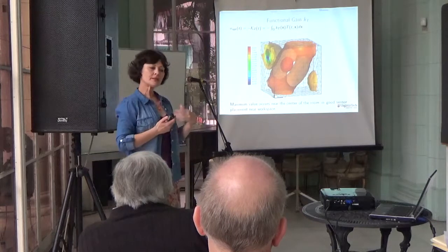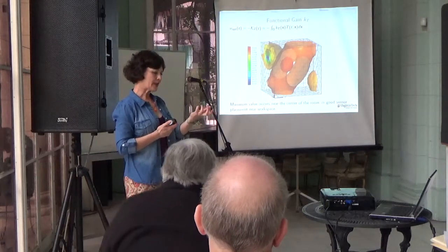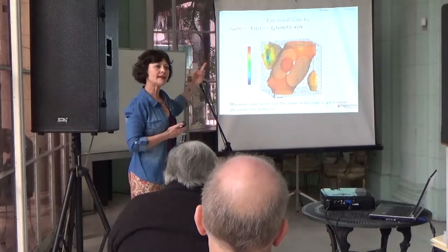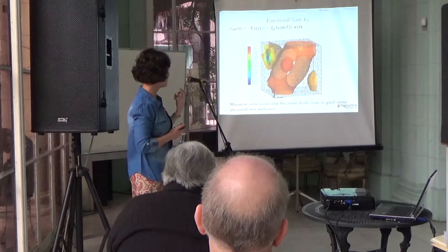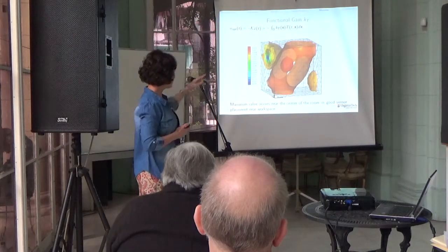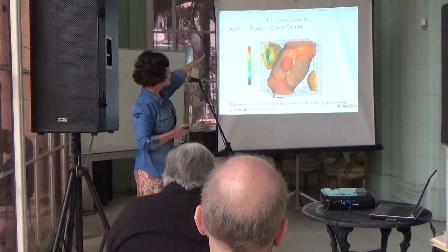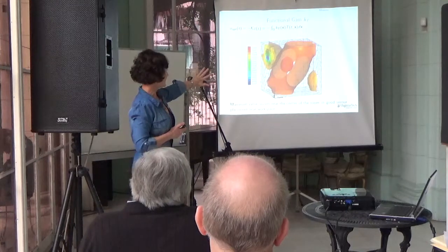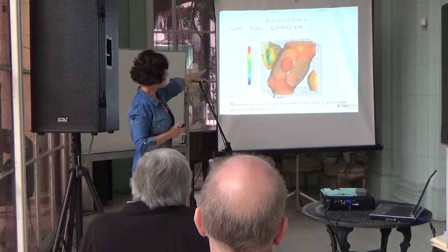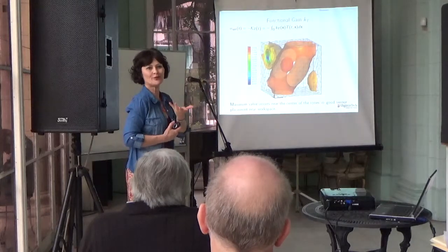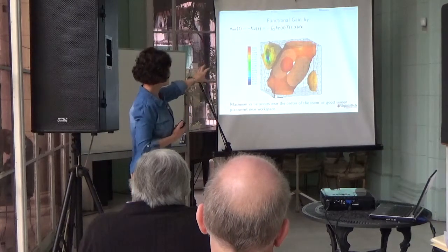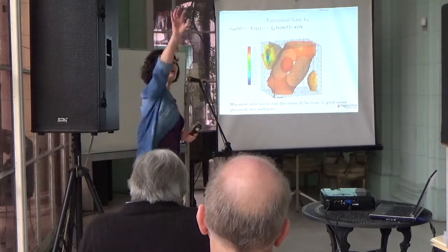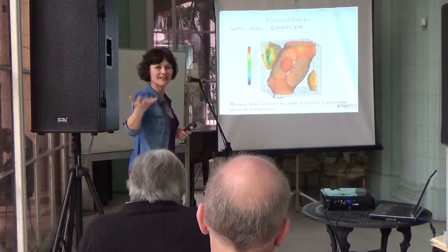Now you'll recall I pointed out that the feedback gain operator that we need to calculate the control has an integral representation, that functional gain. And I said sometimes if we can calculate that, that will be useful. Because it tells us that when little k is large, then the temperature in that region really matters. So this is full state information, and you will see the red dot is roughly in the area where we want to control it. So it tells us that the temperature in that area matters. So if we could put a sensor, we should put it up in the area in the middle here. That's what we should do.